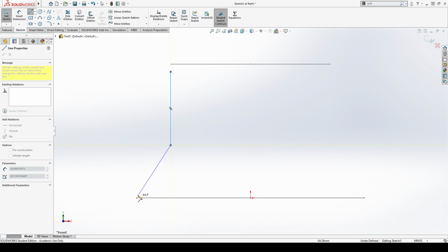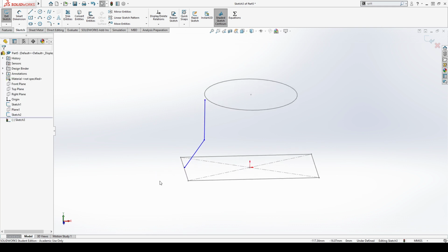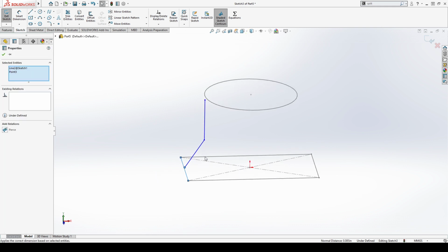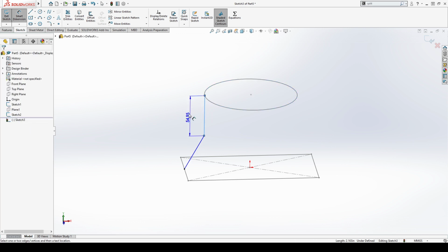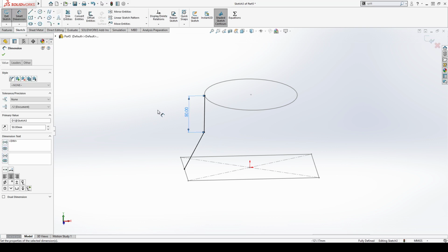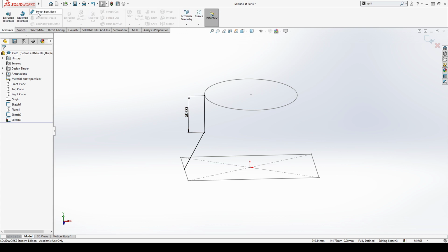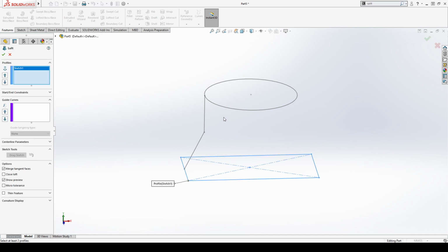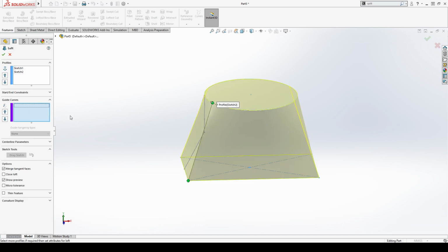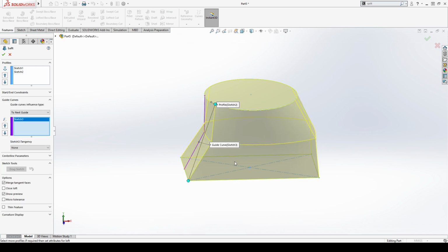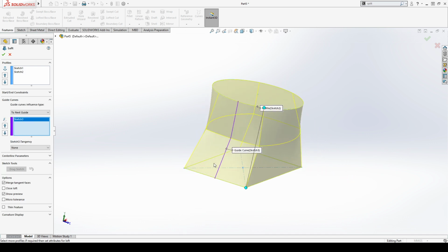And then I want to make this a really sharp transition in my boundary, basically. So I'm going to pierce that there, and pierce that there. And then this is going to be like a 50 millimeter extension that's going to go straight. Cool. So I think this should work. Exit the sketch. Make a loft here, there. Give it a guide curve. There we go. So you can see adding in this curve here.